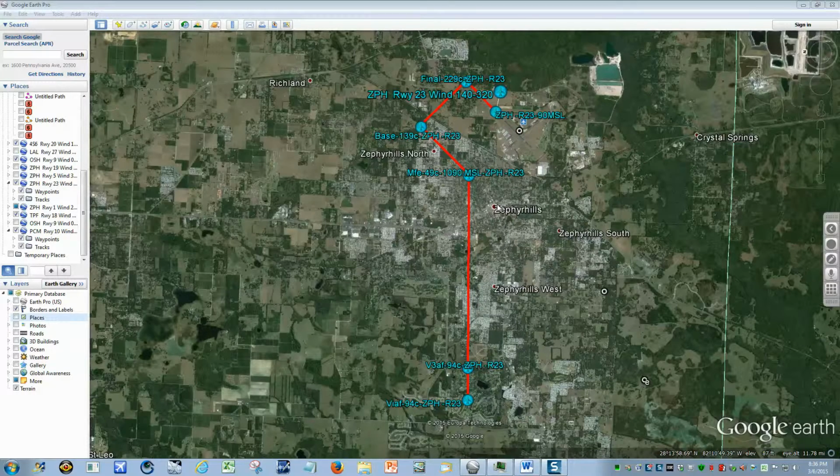Since we are 1,000 feet above traffic pattern altitude at the V3AF waypoint and starting our controlled descent, using our conservative 8:1 glide ratio maximizes the margin of safety by allowing us to glide greater distances to a potential emergency location along the approach path if necessary. Arriving at the V3AF waypoint at 1,000 feet above traffic pattern altitude will allow for a safe, stabilized approach.